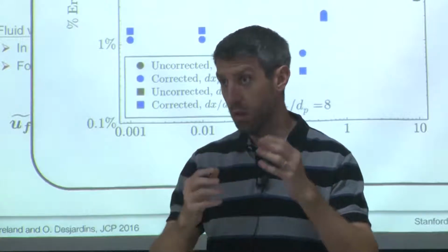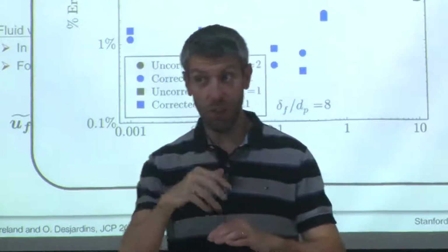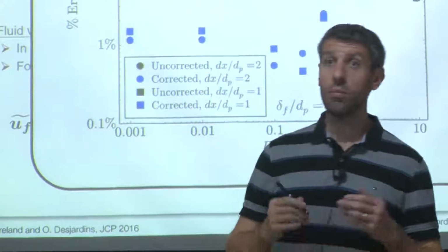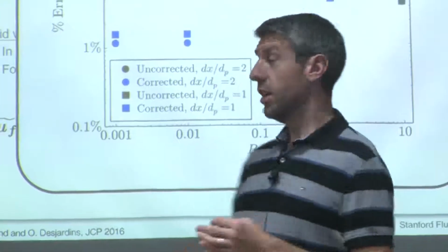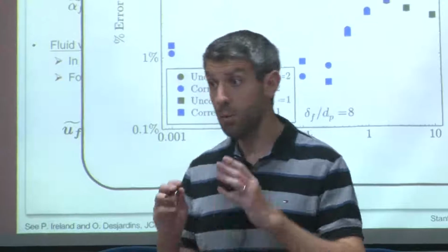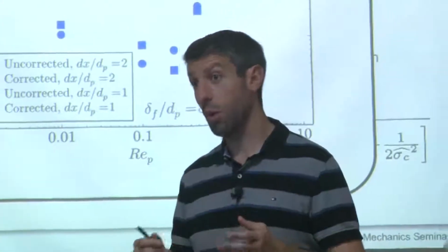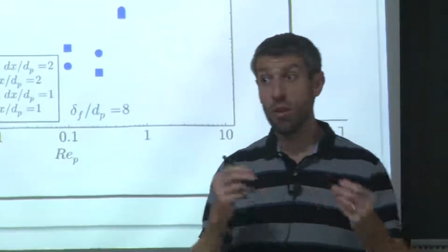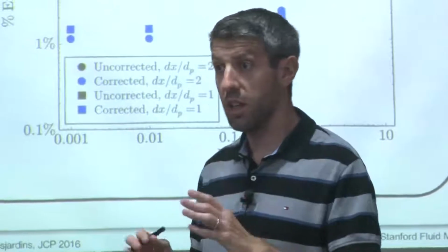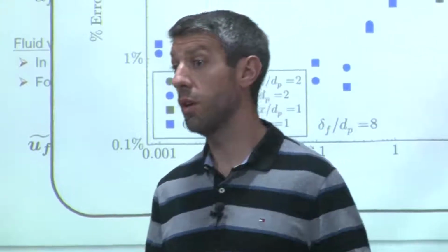It's conceivable. Or alternatively, you could have a situation where some of your turbulent length scales are larger and some are smaller. So if your argument is that using a Stokes flow to correct is not always going to be valid, I absolutely agree. It's only valid in the limit where the particle Reynolds number is small. But there's no inherent contradiction that I see, at least, because we haven't limited ourselves to situations where the Kolmogorov scale is smaller.